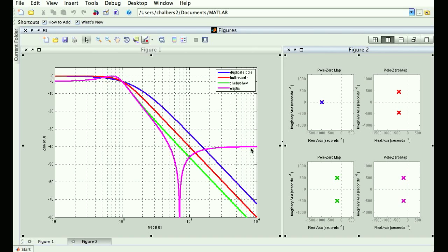So how do you know which one you need? You go trial and error, right? You get some sample data and you try filtering your signal. What does it look like when I filter with a Butterworth or a Chebyshev or an elliptic filter? You mess around with it and you see what happens. Oh, okay. I tried filtering some sample data with the elliptic filter and it looked great. I think I can do that. Or it looked like crap. I can't use it. Okay, so that's kind of what guides you.